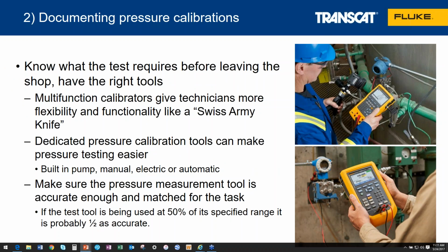Now let's talk about documenting pressure calibrations. So it's important to know what test tool is a best fit for the application. What does a test require? Figure this out before you leave the shop.